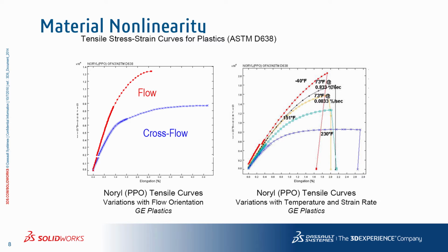The general recommendation is that you get your hands on the most applicable stress strain data for the materials that you're considering using, to determine if the material nonlinearity is even an issue for the strain levels you're operating in. This level can be determined from an initial linear material analysis, and if you decide to use a nonlinear material model, try to find the stress strain data that best represents your environment, and if necessary, bracket the results with two or three different curves to see how sensitive the response of the structure is to this nonlinearity. And finally, it is always good practice to back up your analysis with test data.